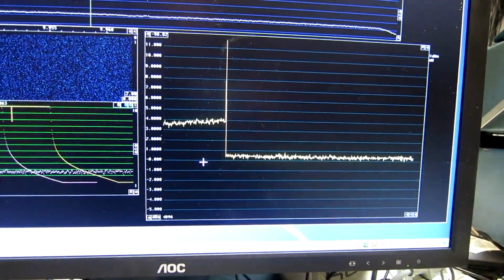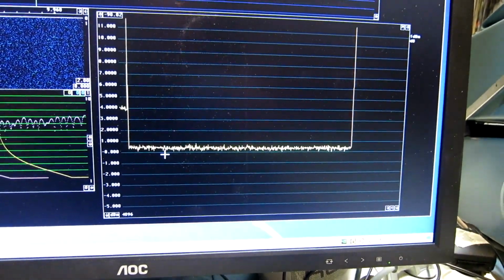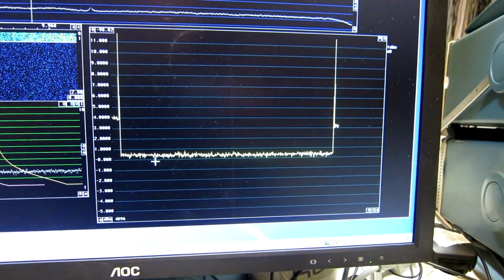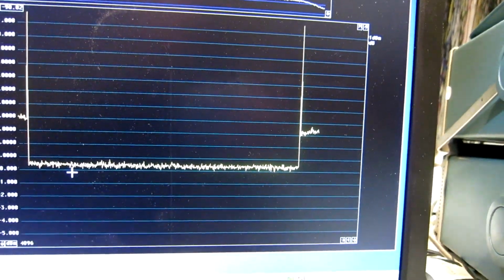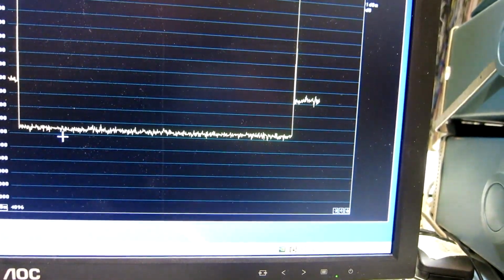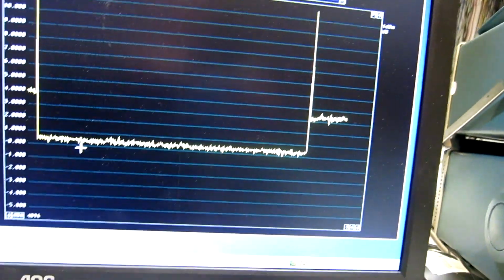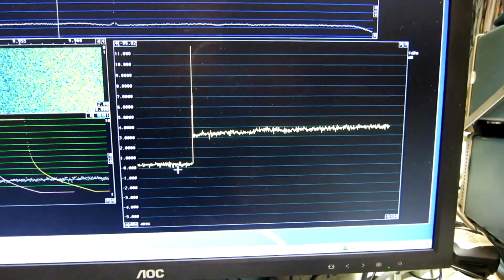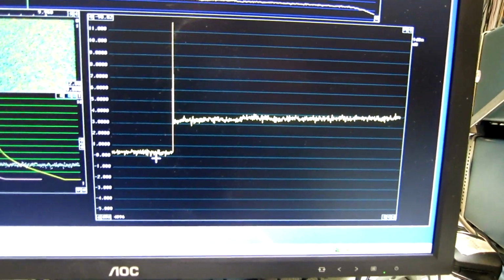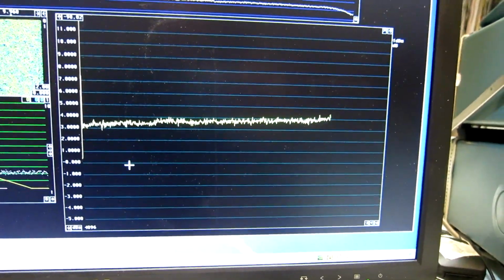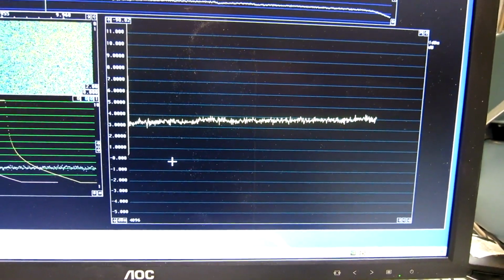I'm running now with 10 dB of attenuation, and I switch to 0 now. And look at what happens to the noise. And I wait a little. It's quite clear that the noise increases with time. Not so surprising, the losses are high, so this capacitor is heated.